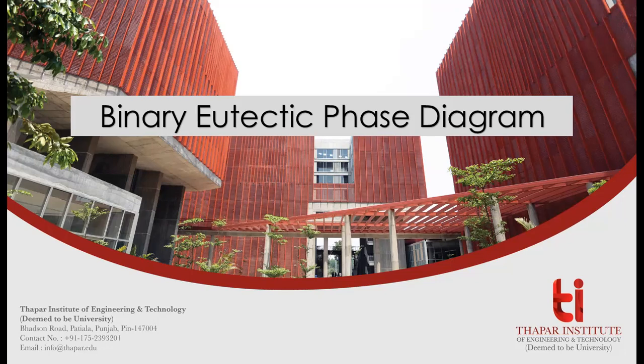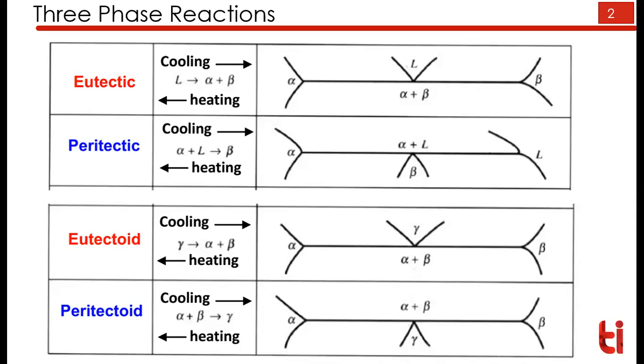So due to that, there are other alloy systems. One is the eutectic phase diagram. We'll discuss this one. Again, this is a binary phase diagram; isomorphous is also binary only. Components are 2 here also, there also. But here these alloy systems are different in their structure also. In the eutectic case the melting points have to be close, but in peritectic the melting points should have a large difference. Based on that, there are 4 kinds of reactions I am discussing here. There are 2, 3 more as well.